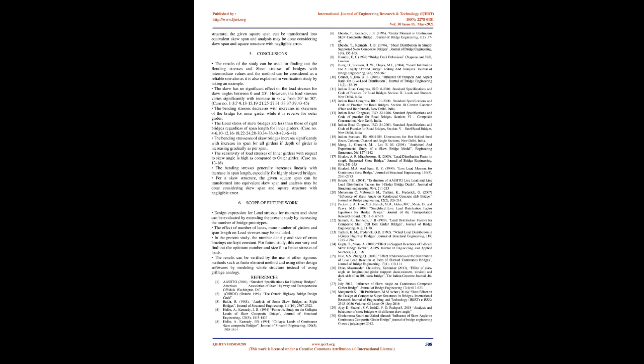Case No. 4-6, 10-12, 16-18. The bending stresses of skew bridges increase significantly with increase in span for all girders if the depth of the girder is increasing gradually as per span. The sensitivity of load stresses of inner girders with respect to skew angle is high as compared to the outer girder. Case No. 13-18. The bending stresses generally increase linearly with increase in span length, especially for highly skewed bridges. For a skew structure, the given square span can be transformed into an equivalent skew span, and analysis may be done considering skew span and square structure with negligible error.